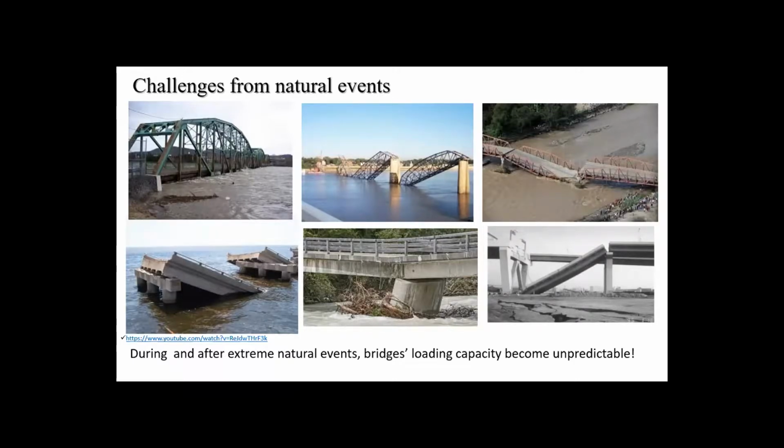One thing I want to mention is that with flooding, situations can become very complicated, because sometimes the forces come not only from the river but from other things, for example fallen trees and other objects. It is also not only affecting the bridge structurally, but also underneath on the river ground, where we have scouring, which affects the load capacity of the piers. This project will not consider scouring. The idea is to look at the superstructure and see how it is conditioned before and after the events.